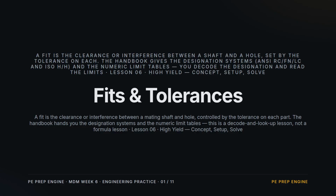Week 6, Lesson 6, Fits and Tolerances. A fit is the clearance or the interference between a shaft and the hole it goes into. Each part carries a tolerance, and how those two tolerance zones sit relative to each other decides whether the parts slide, locate, or press together. The handbook gives you two designation systems and a set of numeric limit tables, so this is a lesson about decoding a callout and reading a table, not about a formula. We'll define the three fit families, walk both designation systems, then read a running fit straight off the printed table.